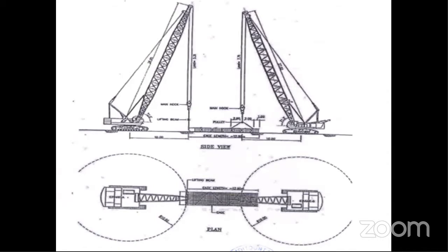So while putting the concrete, it will not reach that touched side. While doing excavation, that reinforcement will get exposed, and as it will be underground, the chances of corrosion of the D wall panel will increase.